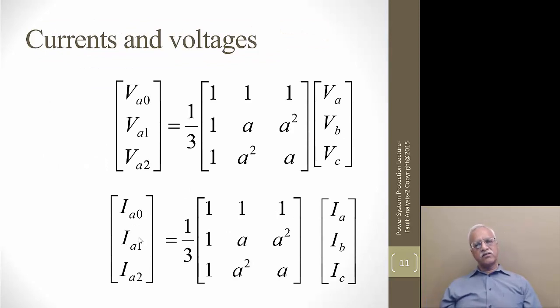Matrix representation also we covered. Here is a matrix representation to get the sequence components from the phase components, and you can similarly represent a matrix equation to get the phase quantities from the sequence quantities.